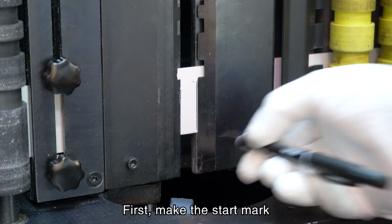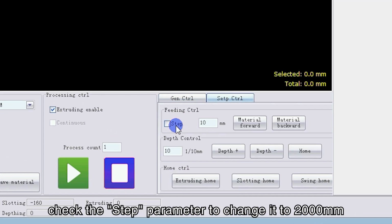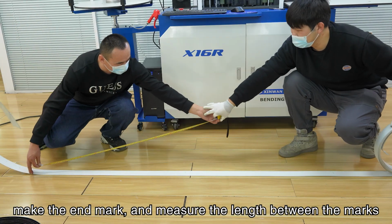First, make the stop mark. Click on the Step Control Switch panel. Check the step parameter to change it to 2000 mm. Click on Material Forward. Make the end mark, and measure the length between the marks.